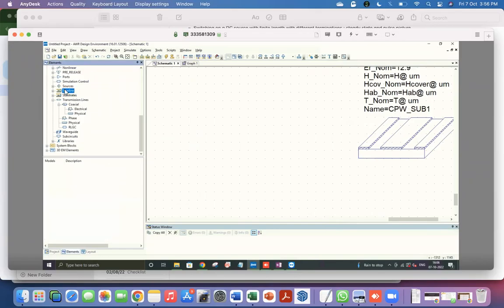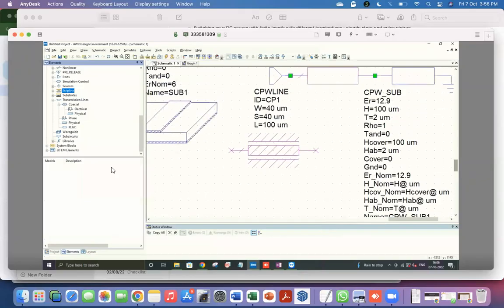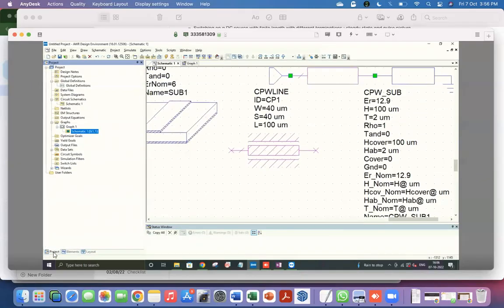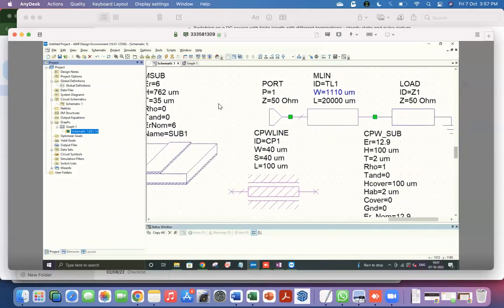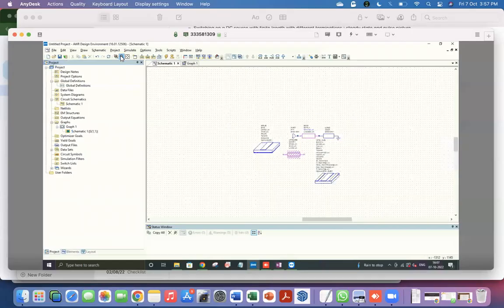Okay, so then same for strip line. I would suggest that you try playing with these things to get familiar with these different objects. And these again are pre-solved models. So rather than a simple electrical model, this actually takes into account these dimensions and comes up with some effective formulas and then uses that to do the computation. So if you're trying to design something, using this will give you closer to the results you have in your actual setup.